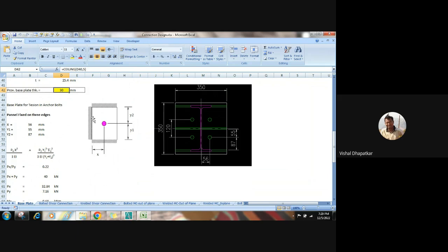One is for this portion, this cantilever beam, and another for the fixed end beam where the load is located at an intermediate level. So we just need to compare these two deflections, right? How can we control the deflection? By increasing the thickness or depth of the section. For any member, when it fails due to deflection, we normally increase the depth of the section, right? For concrete also, if a beam is failing in deflection, we increase its depth. For a slab also, we increase the thickness of the slab so that it will pass in deflection.